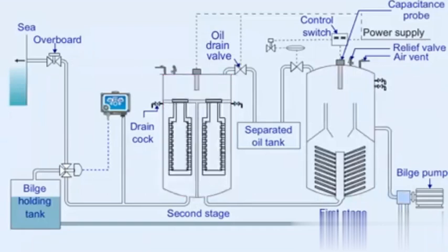The bilge pump delivers clean seawater to the first stage of the separator through the inlet valve. The vent is kept open until all the air is removed from the separator and water issues out. Oily water is delivered to the separator.